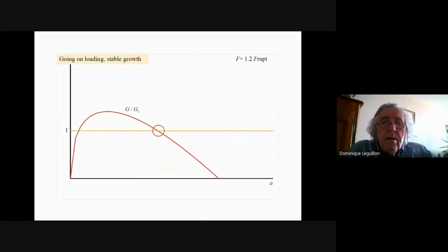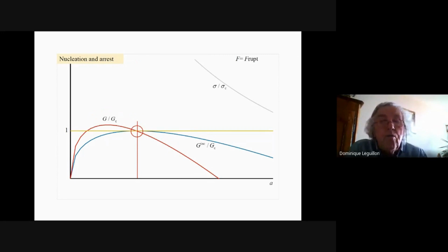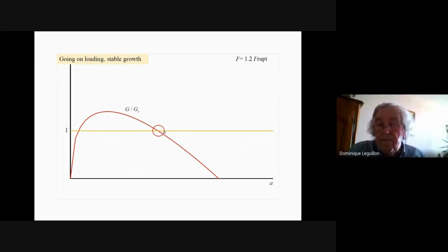And next, if you go on, then you have a stable growth of the crack, okay? You see, you have just to calculate G, and you see that G, as you increase the load, the curve that is here will grow like that, and then this point will move stably to the right. You have then a jump followed by a stable growth, but this is a quite seldom situation, met in rocks only.